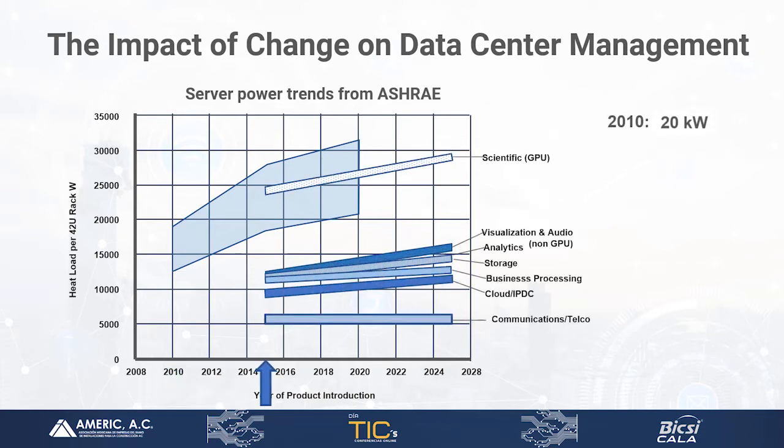But if you're operating that data center and then now have to plan for IT equipment in 2015, the roadmap for IT equipment as published by ASHRAE changes completely. A lot of the power densities are lower. ASHRAE is reporting the information in a different way. They've broken it out by server type, and the trends aren't as steep. So if you're planning now in 2015 for the same equipment, you may have to plan only for a 2.5 kilowatt range of IT equipment.